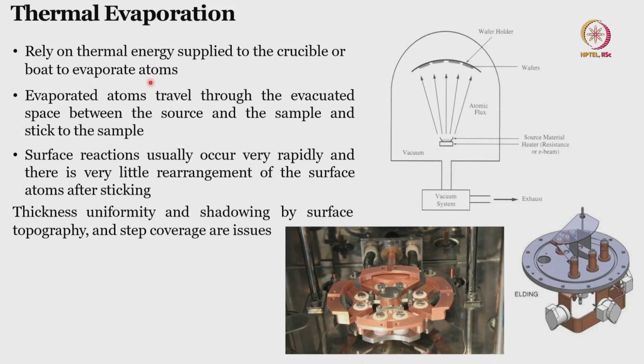One is that you can heat the film during the deposition. That means your wafer holder or substrate holder has a heater. We have seen earlier that there was a heater indicated on the substrate holder. Then the rearrangement of the atoms can be made better. Second, you can take out the deposited film and anneal it in a chamber. You heat it in a chamber, and then you can see that it has a polycrystalline nature.